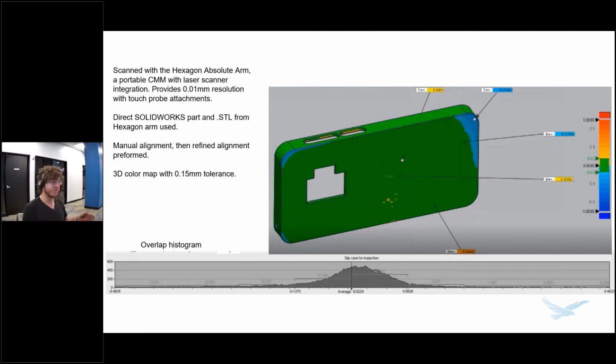So we go from the scan data, we capture our product, we digitize it into raw point data, we convert it into a mesh, so something that we can now actually bring into other softwares and start working a little bit better with. We take that mesh, convert it into a solid for our reference bodies. Now we have this solid body we can interact with other solid bodies with. We actually designed our phone case, so I actually put in our engineering caps and built our product.